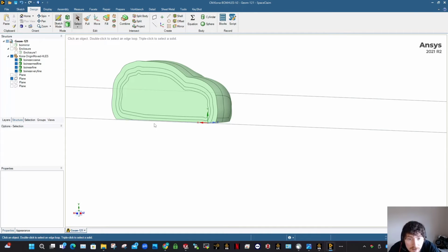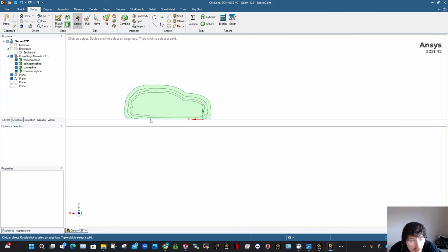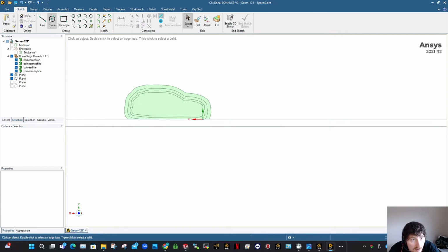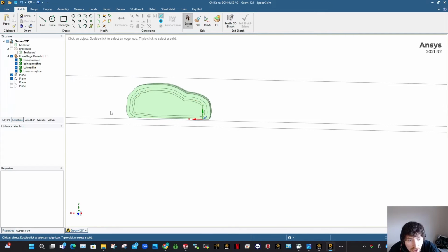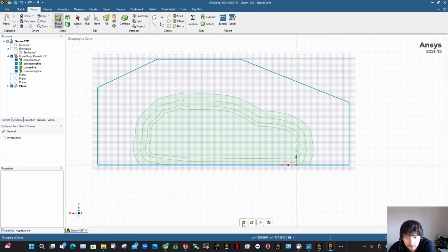So the best way to do this is to come in here from the side, maybe turn on the symmetry plane there, and then just draw a shape outside of this. You could even select the outer edges there and then use this offset tool. So I'm just going to draw that now, 1,000 mil. So I'll be back in a sec. Cool. So that's about 1,000 mil outside everyone there. You can draw it whatever way you want. It doesn't matter. So then return to 3D.